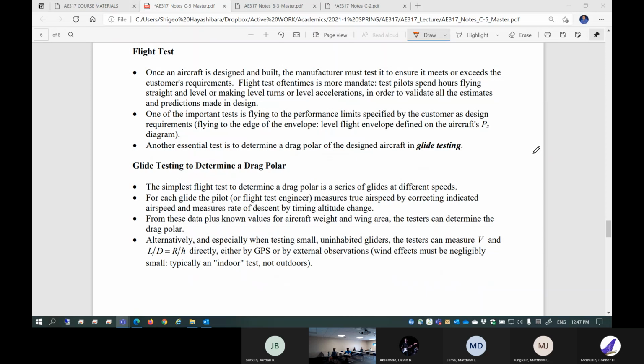So flight test, I'm talking about the actual manned airplane. Flight test needs to be conducted. Most of the flight test is very simple, repetitively boring testing, such as airplane takeoff, level flight, constant speed or constant acceleration, level flight, accelerating flight, repeatedly with different altitude. Very boring test. Day in, day out, test pilots need to do such things to determine certain characteristics.